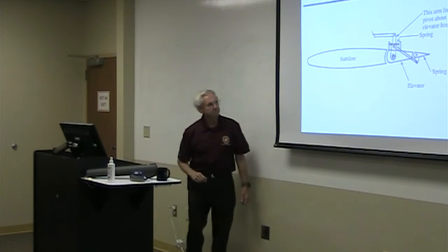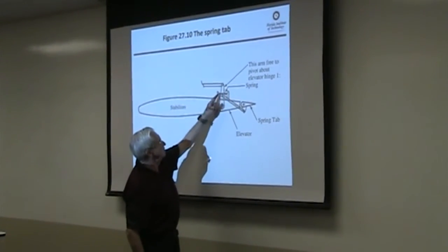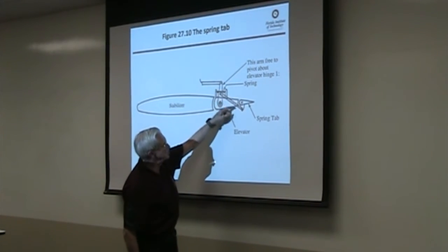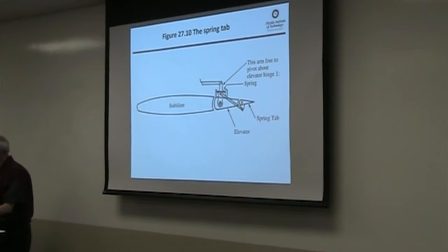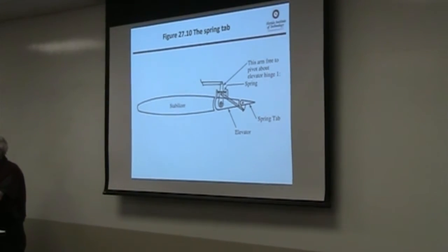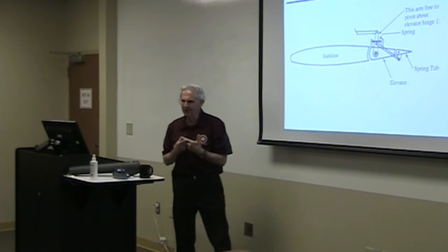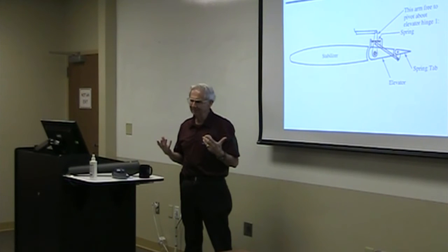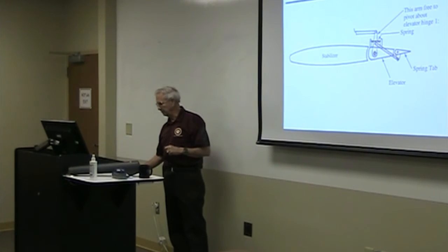Well, here's the spring tab. See, in this case, again, this is still a pivot. We've got springs here, so you move this control while it compresses or stretches the spring and moves the tab. That's the spring tab. Again, that spring has a frequency. And so you have to make sure that frequency doesn't get together with other airplane frequencies and cause flutter. Structural dynamics, they call that.